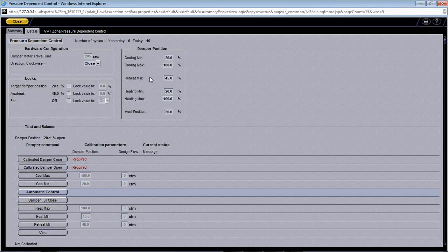Okay. Let's say that the rooftop is, the boat is going into heating mode, but three of the zones are actually requiring cooling. They just aren't too far out of whack. We don't want to be discharging a minimum amount of hot air into those zones. We want no air going into those zones at the time. Now, you still need to meet your ventilation codes, but with under 20-ton systems, it's not that important relative to big VAV systems. So ideally, you want to put this at 0% for both your minimums here.